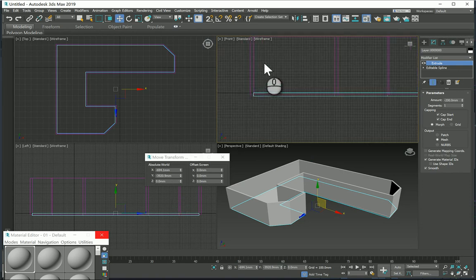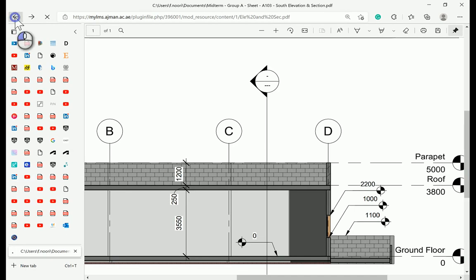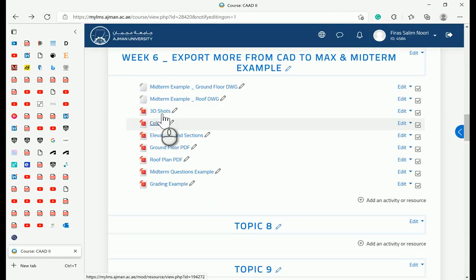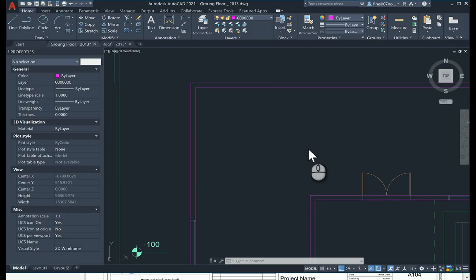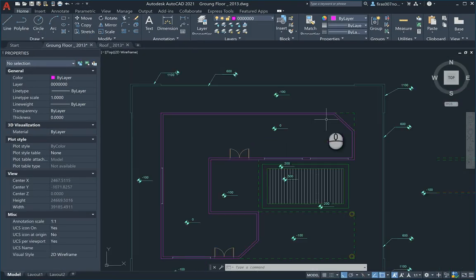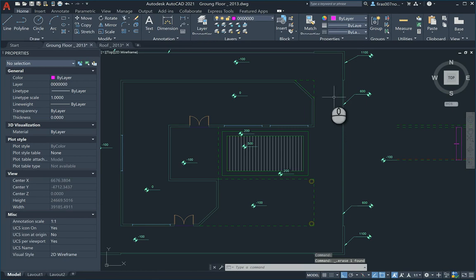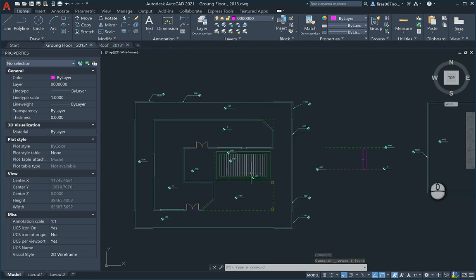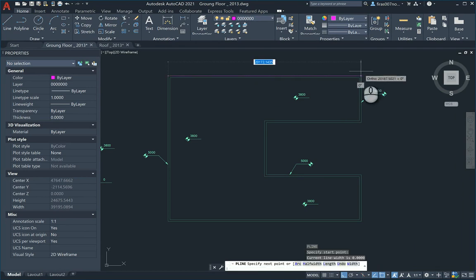Now the upper floor, if you go back to the 3D shot, sorry, the PDF, you're going to see that it is all the way continuous, with a U shape without those chopped parts. So back to CAD, we have it already there. I'm just going to get rid of those magenta things in here. Some people suggest I'm going to trace those. Lots of my students do, it's okay. And some people just say, no, I'm going to polyline those. Both are correct, and then you're going to move them there.